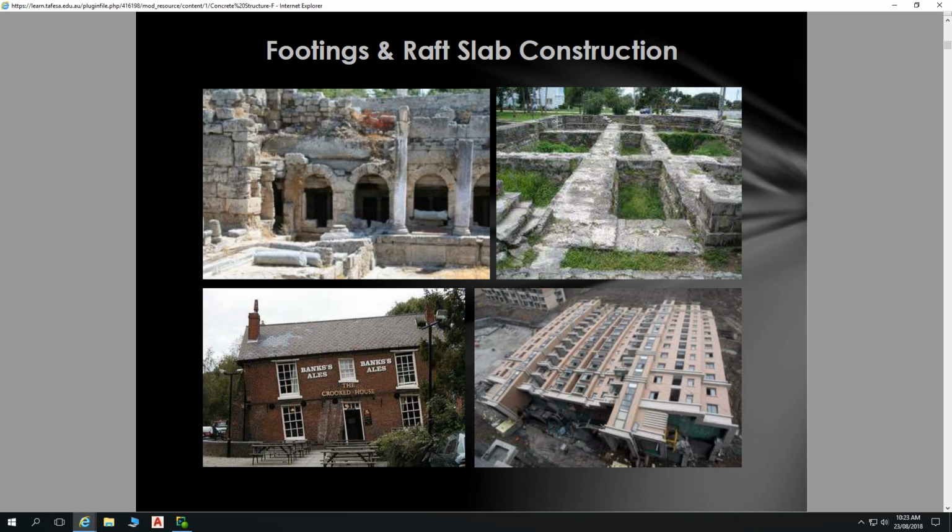So some formwork. That formwork has to be incredibly sturdy, and also what's important is that it has a really smooth finish. Important for a couple of reasons. One, because the finish of your formwork is the finish that you get on the edge of your concrete. Not all faces of concrete are formed by formwork. You have your top face, which is troweled off, and we'll talk about that later.